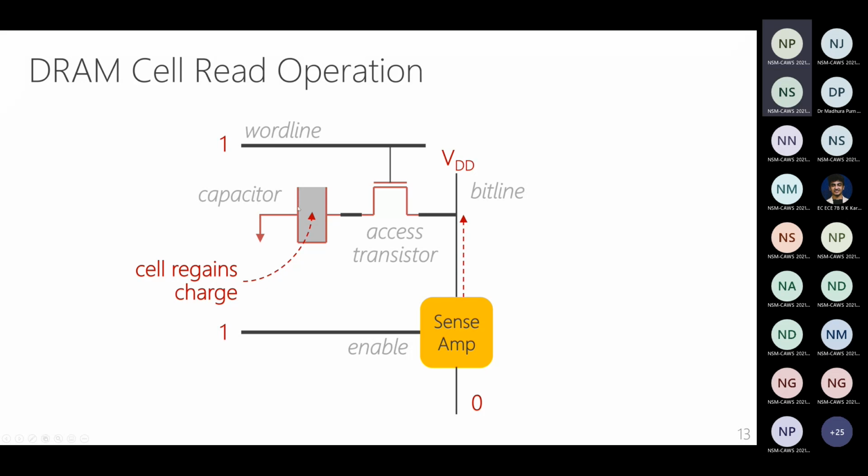Okay. In any case, here we started with a cell which was fully charged, and we saw how after this sense amplification process, the cell essentially returned to the fully charged state. You can again imagine a cell which is fully empty, and if you start with the fully empty cell and connect that to the bit line, now the reverse will happen, right? The bit line will essentially lose charge to the cell. So the cell will gain charge, the bit line will lose charge, which means the bit line will now go to half VDD minus delta, and the sense amplifier essentially takes the top to 0, and the cell will again lose all its charge to the bit line because the bit line is now being driven to 0.